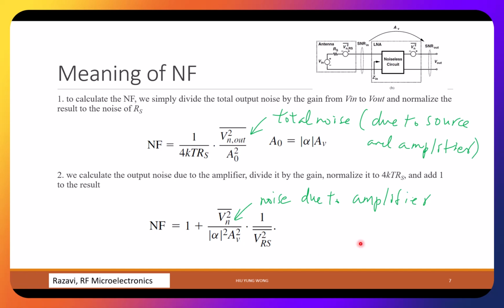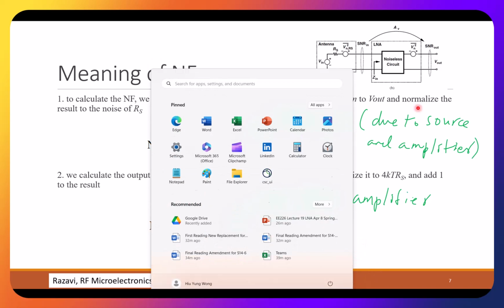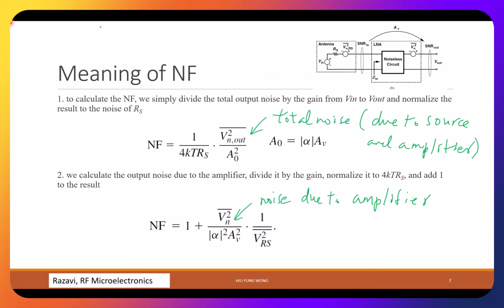Yeah. When you're trying to design your amplifier and figure out, or I guess minimize your Vn squared, kind of working with some sort of noise range, right? Because it looks like the noise factor depends on the. I mean, noise of the input is something you probably cannot change because it is usually like a characteristic impedance that coming in, right?